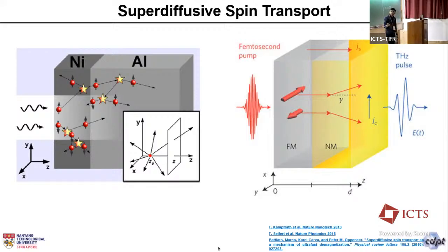So these are ultra thin materials, 3 nanometer each. So it's way beyond the penetration length of, let's say, the metals that we are using. The typical length scale that we use in this heterostructure is around 2 to 3 nanometer for each layer. Yes, so we are beyond the penetration depth. Yes, correct. But again, these are ultra thin, right? So the temperature gradient will not be that much if we are talking about 3 nanometer. But yes, the Seebeck coefficient will also come into the picture.